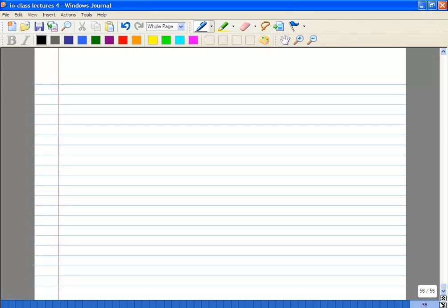There are a couple of other circuits for increasing it, but we won't worry too much about them. So now we have considered a single stage amplifier. Now suppose you want a very large gain and also large bandwidth. We know that a single amplifier has the gain bandwidth product, which means if you get large gain, you will get low bandwidth and vice versa. The easiest way to get both is to cascade many stages. So let's look at that.